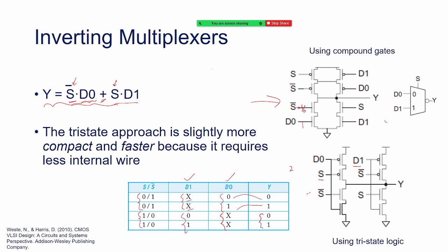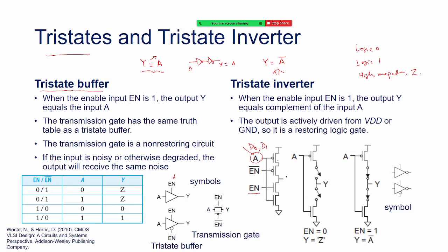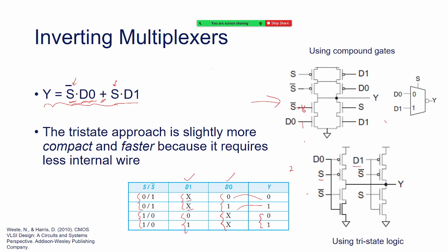Right. So good question. So again, come back here. What we see here, there is a data input here. This is the tri-state inverter. We know that. Yes or no? Yes, sir. So just remember the circuit configuration. We take two bottom transistors, two up transistors, and on the top transistor we have a data input A coming, and this is enable and it's complementary to the middle two transistors. So this becomes one tri-state inverter. So we have done the same here.